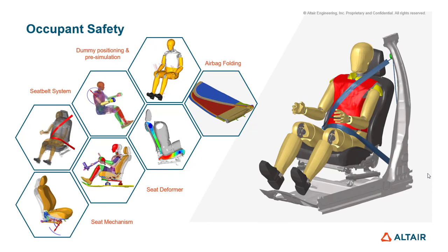So it starts with the creation of a table, and then simple fold, then zigzag fold, roll, tab, and the final step is fitting the airbag into the canister or the housing.